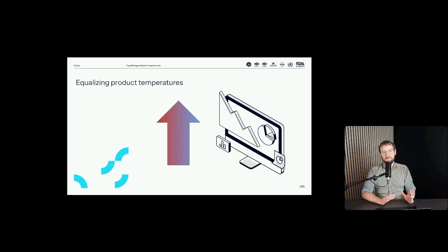When you start to get below 10 minutes, preferably 5 minutes, you pretty much get all of the information that is both valid for when you're doing stability studies and when you're doing very fast events, such as door openings and so on. For stability studies, where we'll just try to measure for a period of time whether the general temperatures are within levels, and during power failures, those events are normally very, quote unquote, slow. So often you can get away with a measurement interval of, let's say, 15 minutes.